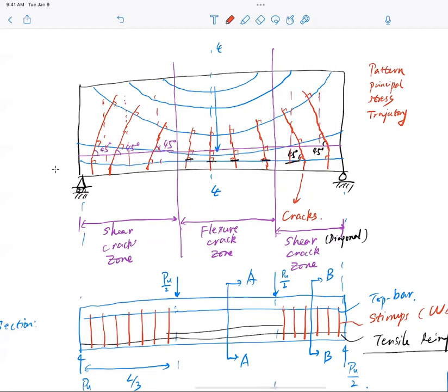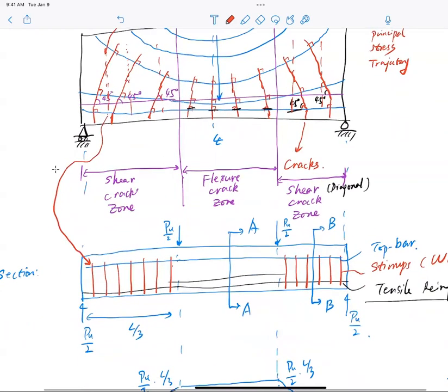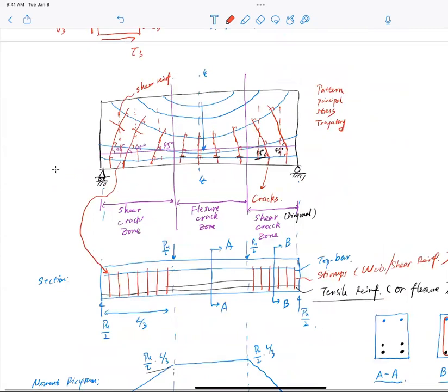And that's why all the stirrups you see are straight line, just to show you they're the same thing, okay? So these are the shear reinforcement. And that's why they are straight, they're vertical. And you say, Bob, isn't it weird? Would it be better if I do a reinforcement like this, and just stitch them like that and pull the reinforcement through? It would be very hard to do that in terms of construction. So we do vertical, okay?